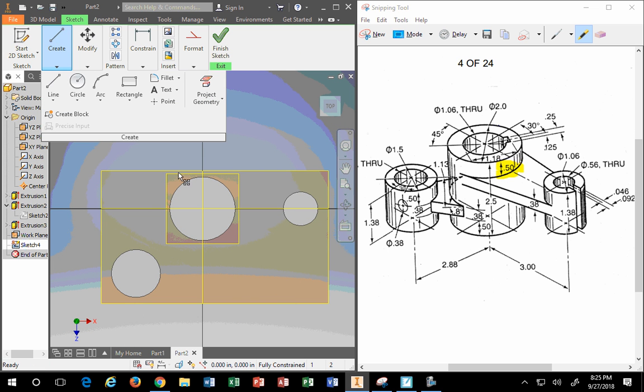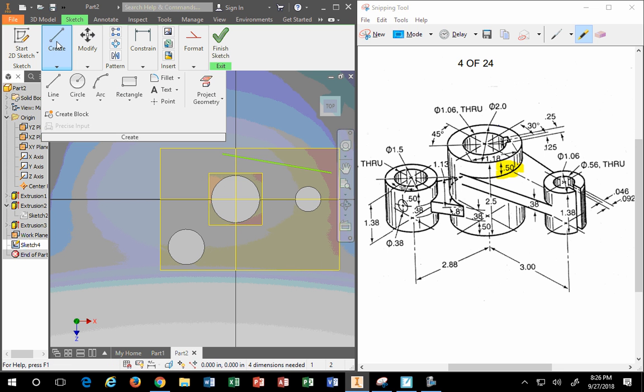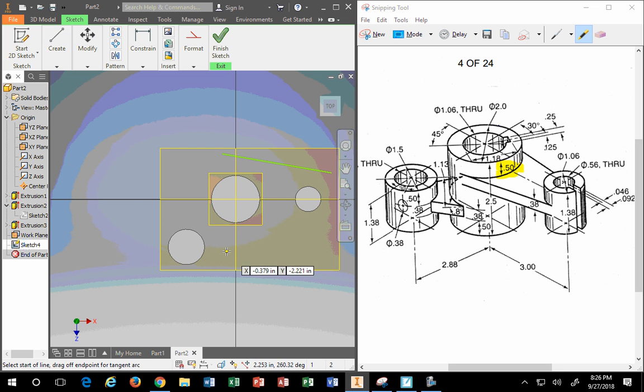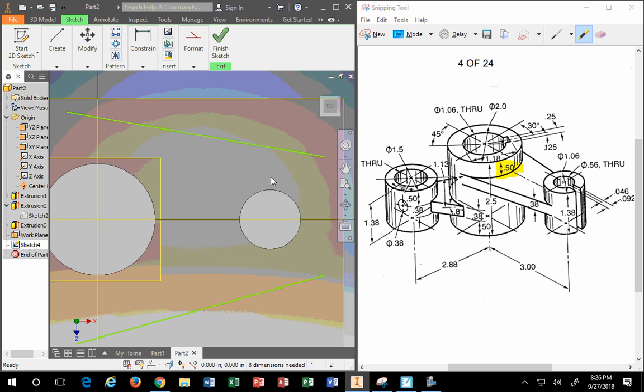I'm going to go ahead and create lines. And just like with the other example we discussed in class, that inclined plane project, I do draw my lines far, far away from everything, because tangency is difficult enough as it is to find.